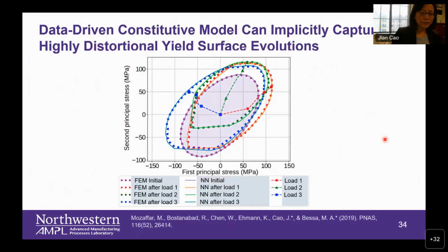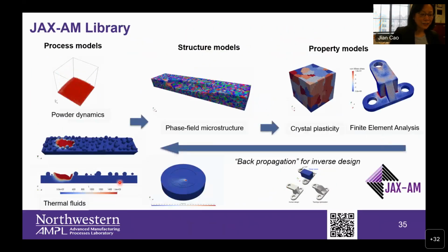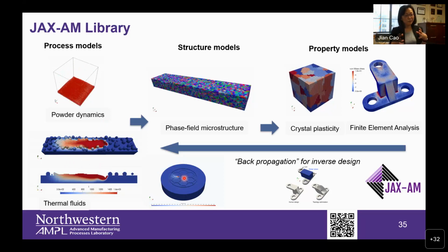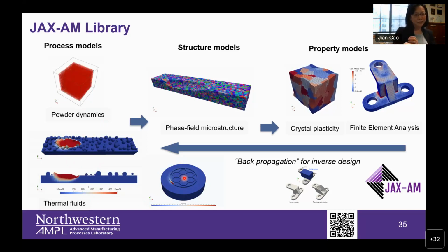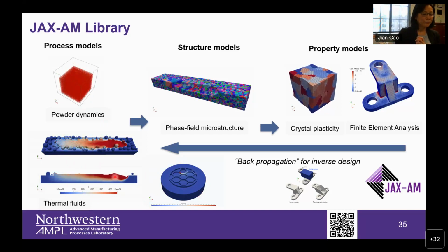And that's why in the current development, I think I have, sorry, let me try to get to that. So for example, the differentiable simulation I showed earlier was just at the part level. At the part level, the temperature input is very much just a Gaussian temperature to represent the laser beam. But the little details, like the particle interactions with the melt pool, we didn't capture. So the goal at this level is to use this as an input to that one. The part level could still be computationally efficient for the design, but nevertheless it's going to be more accurate with more physics involved.